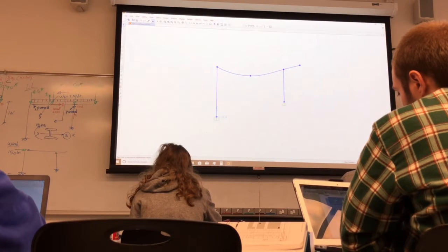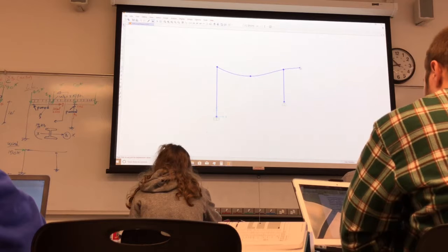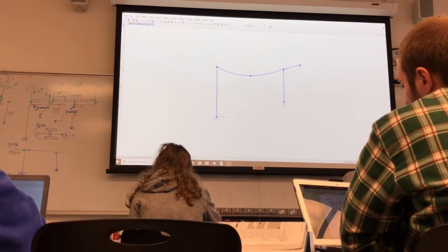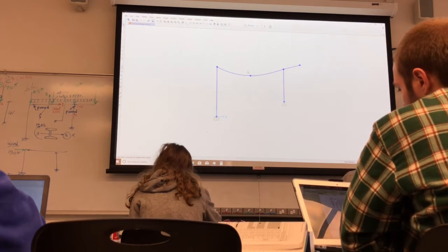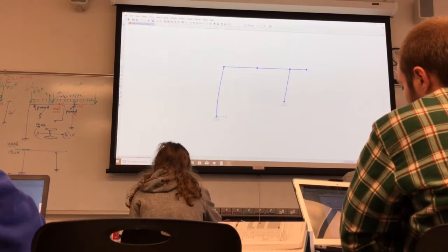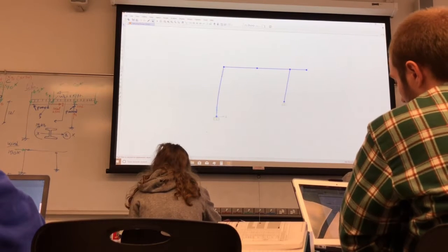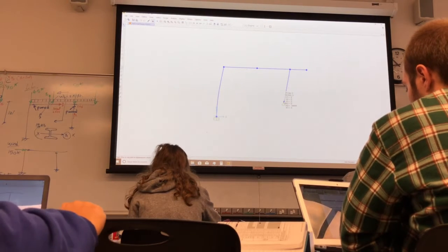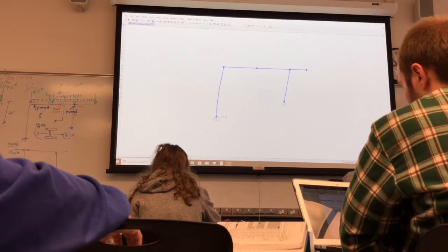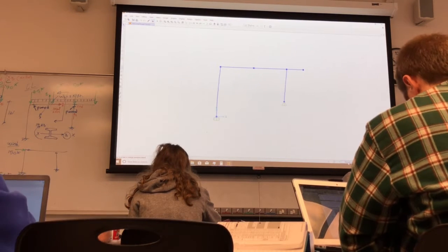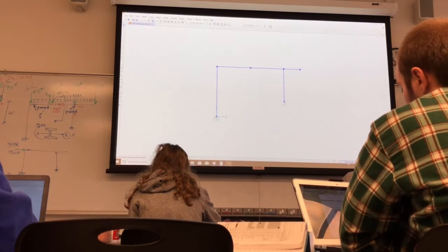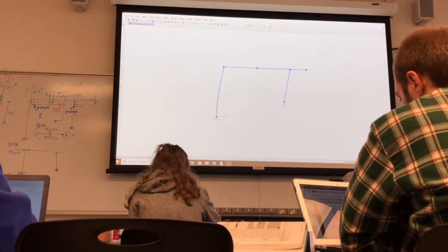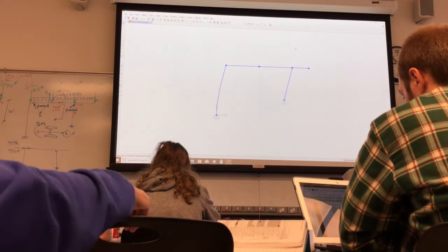Snow. You see snow, we didn't have a point load here, so that's why in snow this beam is sagging here. And then you see the horizontal ones, that's earthquake, that's wind. So you see that's fixed, this is acting like a cantilever. See that's fixed, so 90-degree angle, there's no rotation. This one is rotating. So you see it can also move. And wind and earthquake would look the same.